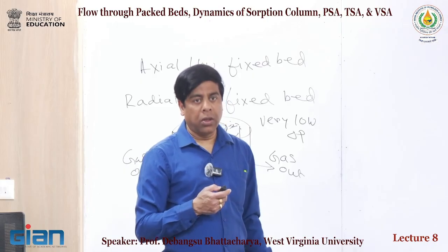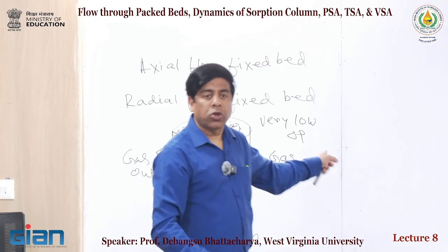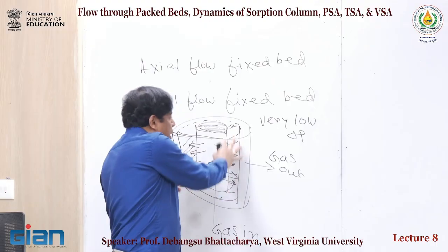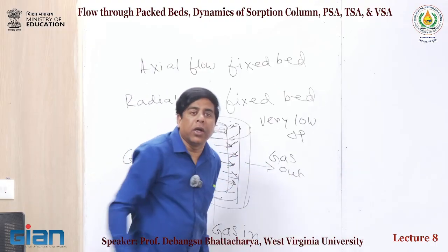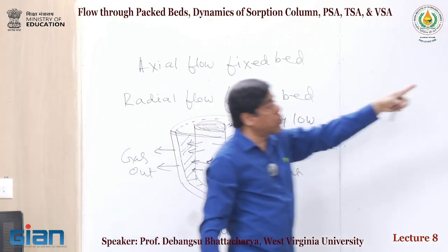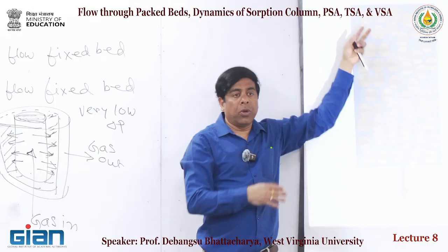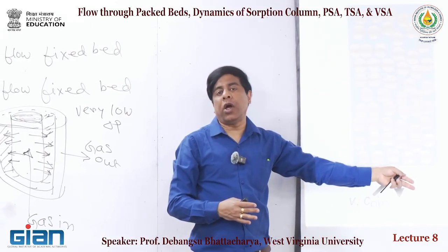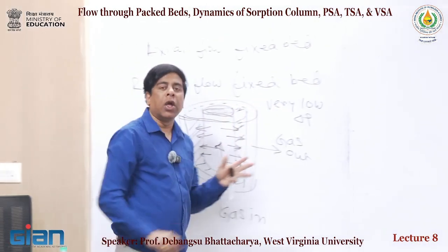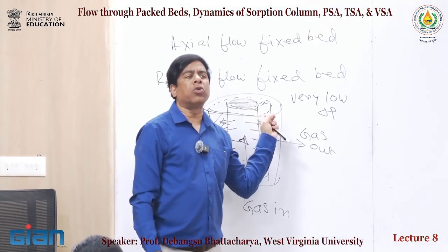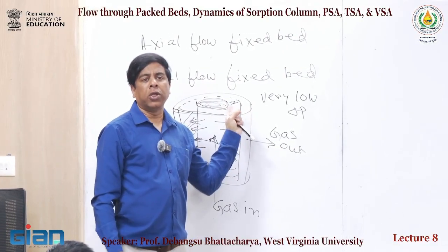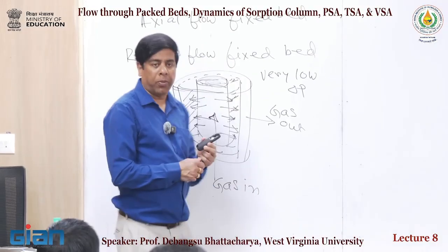This is also, as you were mentioning, that in terms of the height, you can make it wider instead of making it a very tall tower. Once you have it very tall, you will see the pressure drop is also very high. So here it gives you the advantages of doing it this way. But these things do not come without a challenge. One of the challenges, again, that we know is the channeling problem.